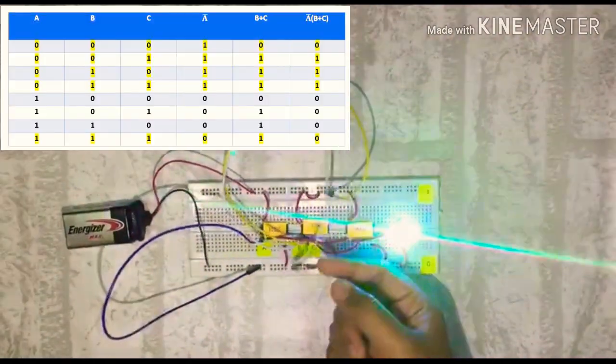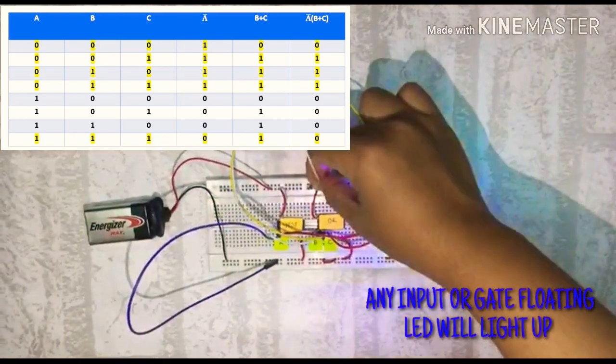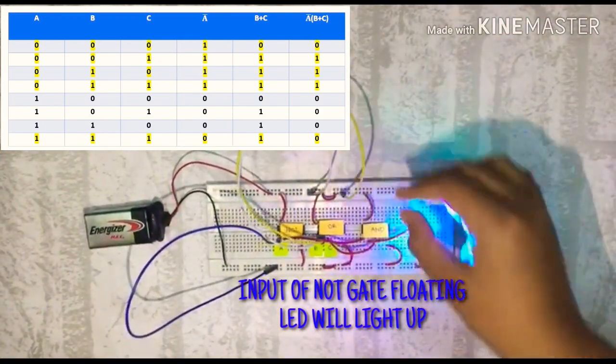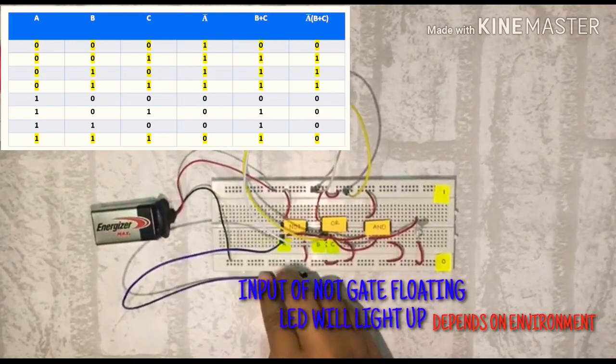We try for output 1. If any input of the OR gate is floating, the LED still lights up. But if the input of the NOT gate is floating, the LED may still light up, but it may even change depending on other conditions in the environment.